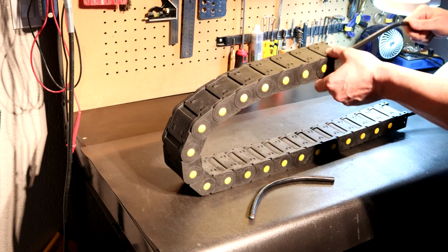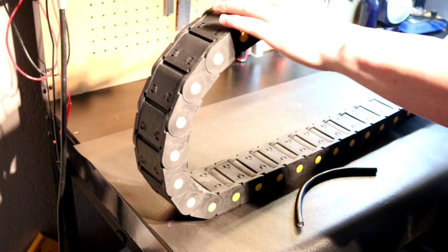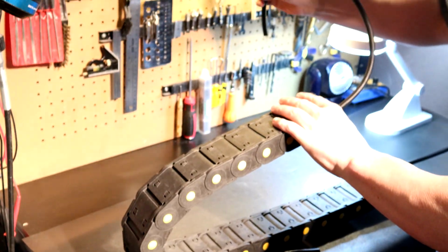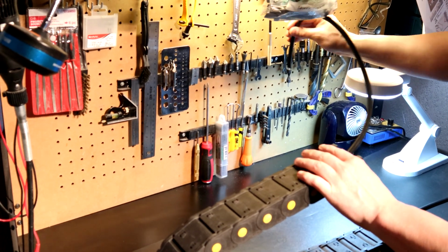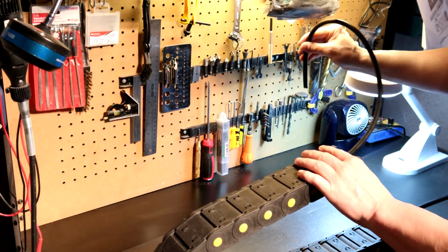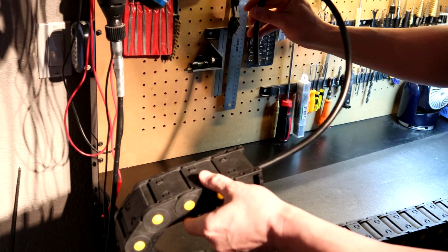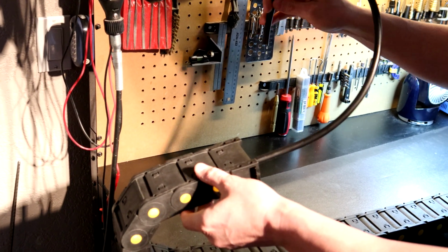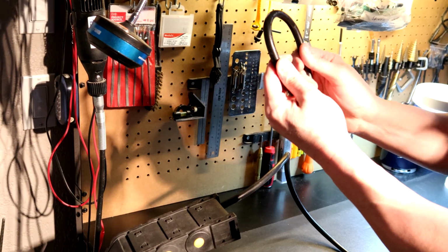So the thing is very simple. Once the cable is actually set in the chain, and you figure out how much cable you actually need, you can see you can bend this virtually anywhere you want. You're certainly not going to put stress on it when you're right here. This is nothing. It's when we come over here and we get tight, that's when most guys have stress. They come back over here, and if they're too close, they're going to do this. They pinch the cable, and that's what fails.